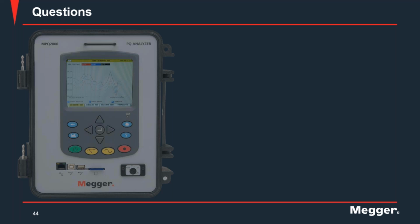Then we have IEEE 1159, which provides the recommended practices for monitoring electrical power quality. So if you want to record your measurements, then you need to look at this standard. Then we also have IEEE standard 1459, which gives you standard definitions for the measurement of different power quality terms under sinusoidal, non-sinusoidal, balanced or unbalanced conditions, and that standard is IEEE 1459.